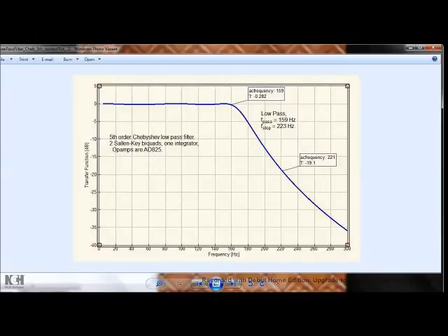But here at the passband edge, at our passband frequency 159 hertz, we're down minus 0.28 decibels. We're only supposed to be down minus 0.25. That's probably a problem of not getting exactly the correct magnitudes we need for the exact profile specified. We can massage our design a little bit and we can get it closer, but this is pretty good.